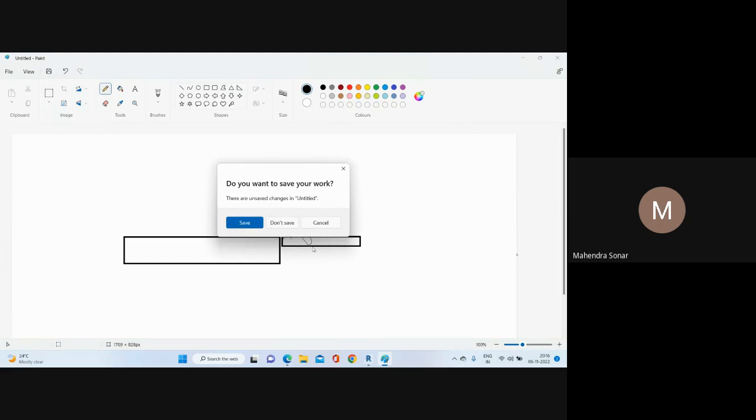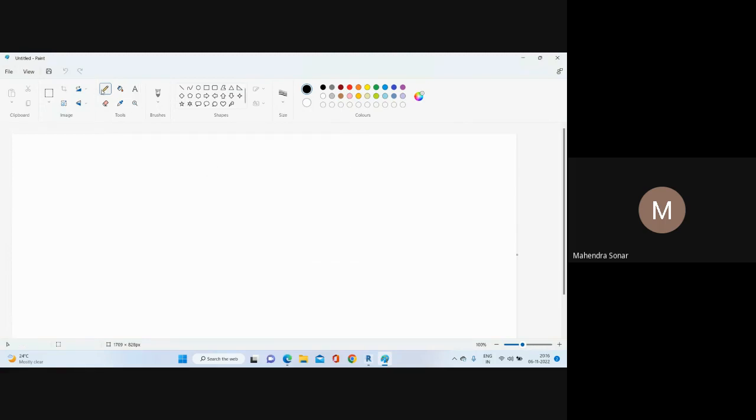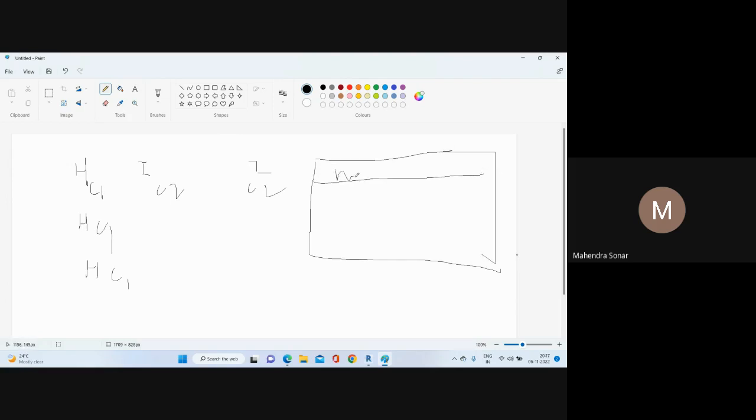Just click new. So this is my column. All of these columns are C1, and this is my C2. I will assign C1 here and C2 here, and then I will provide a table. This table is called the member schedule. The first tab is member mark, you can say mark, then here size, and here you can say description or remark.